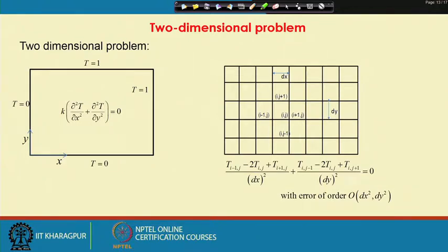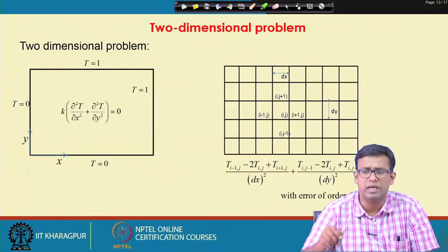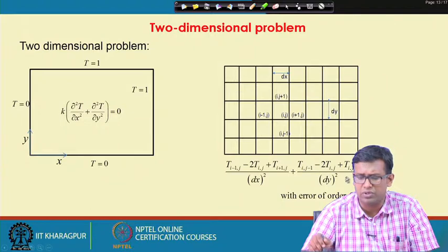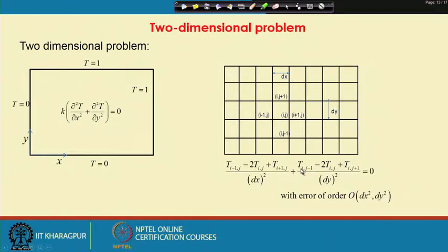So, we will use an idea like that. In case I use a guess solution in y direction, this is only a difference equation in x direction, and this will give a tridiagonal equation in x direction. So, if I have temperature known at these points, within this particular line, this is the tridiagonal matrix, which can be directly solved using TDMA.